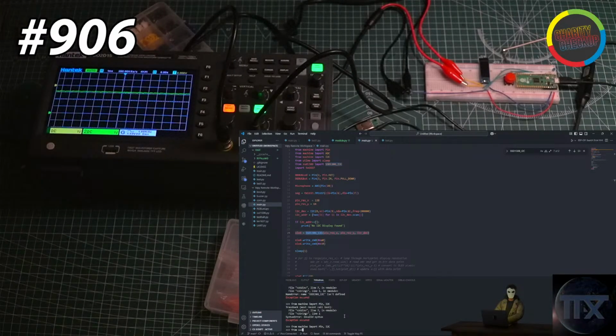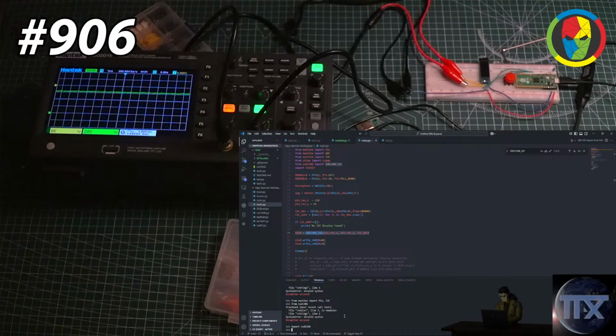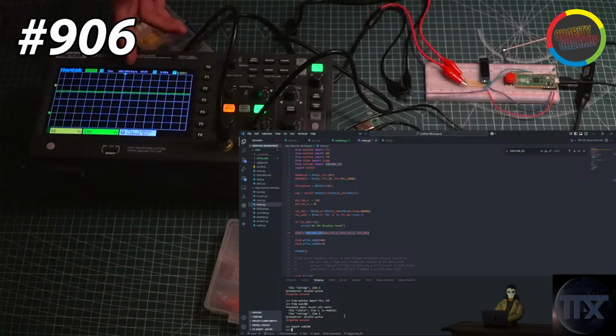That's what I'm saying, right? That's precisely the question I had. Why would the scan last for milliseconds? That's why the long time didn't make sense. You should only see less than 60 bits of information. Exactly. So that's what confused me. That didn't make sense to me for a scan on I2C to go on for milliseconds. That is an incredibly long time. I should have probably specified.